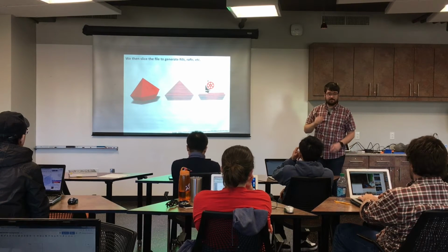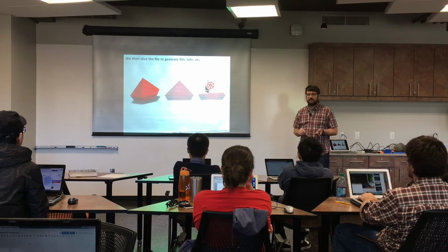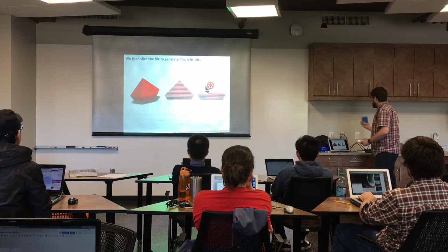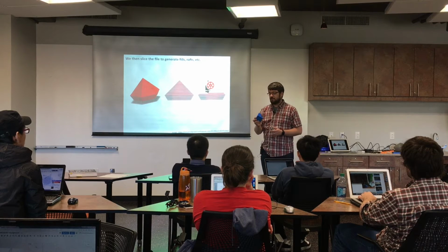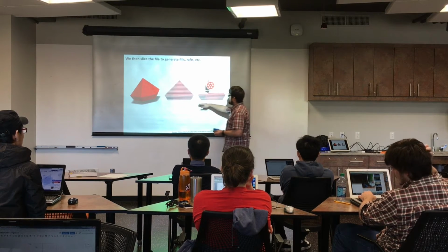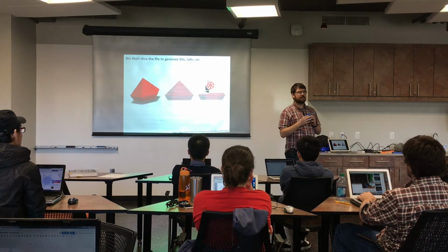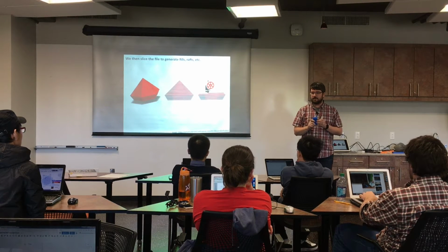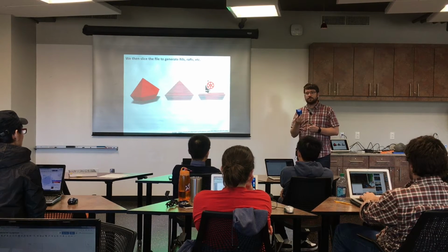And then you have to slice the file. This is where some of the magic, I would say, is in 3D printing. If you want to have a thing like this, it had to be built up in layers by the printer. And so the solid model was this shape, but now we have to slice it apart into layers that are the height that the printer is going to print, which in this case I think was maybe 0.3 millimeters or something. It wasn't very thick. So it does that, and it also generates any internal structure.